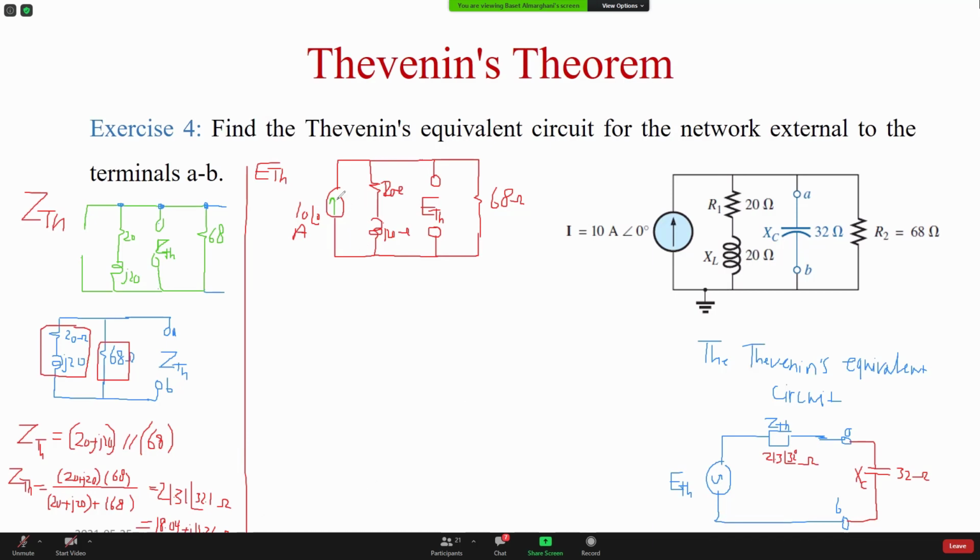Now when we do this analysis here for the Thevenin, usually look at the circuit. If I have one node, I use nodal analysis. So I'm going to use nodal analysis again. So this node is actually the ground. You can use mesh, you can use other techniques, whatever technique you feel is the easy technique. So this is V0. This is the node here, which is the same as this, the same as this, and the same as this. I'm going to call it V1.